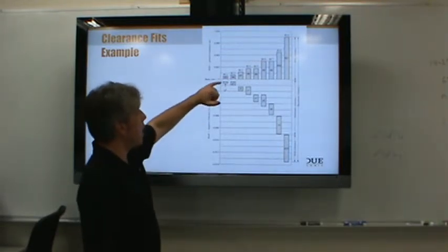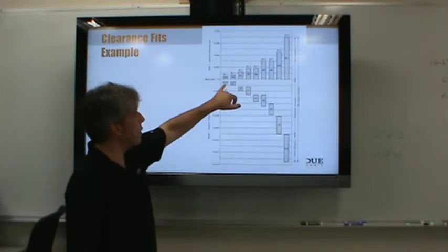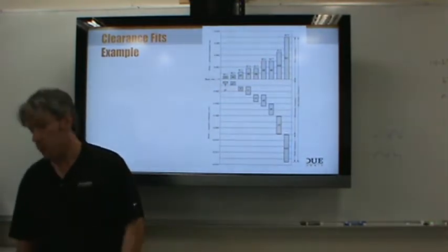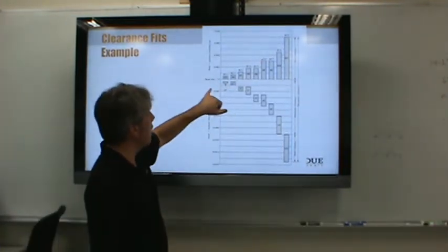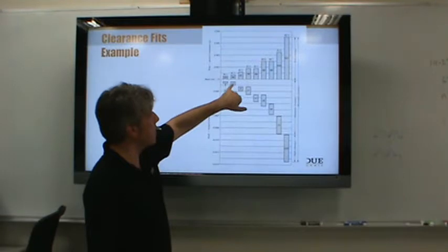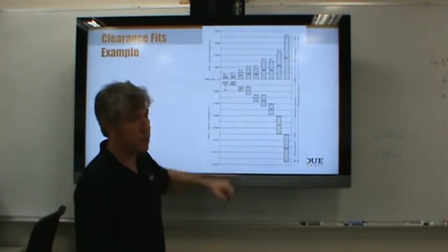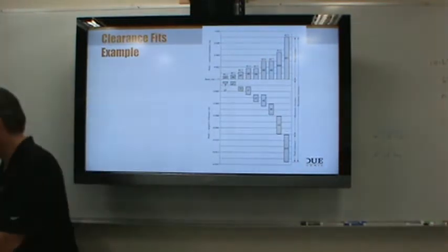But notice the shaft always has to be undersized. In fact, we could look up this clearance if we have RC1. No, they've got RC2. Let's move over to RC2. Notice it looks like the tolerance on a 2-inch shaft is under by 1 thousandth to about a half thousandth. It looks like this may be 4/10 thousandths or so the way it's drawn. Let's look and see if that matches.